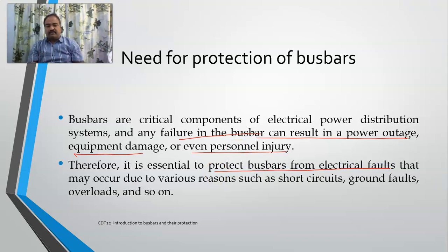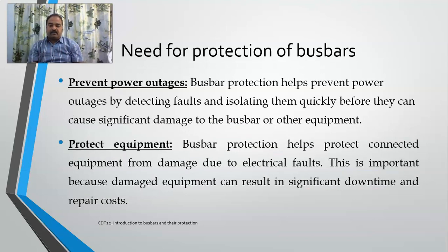Electrical faults can be of different types: short circuits, ground faults, overloads, whatever it might be. So you must be careful to protect your busbars all the time. A quick review of why we should go with specialized protection of busbars. The first thing is to prevent power outages, because we need to detect faults immediately and isolate them quickly.